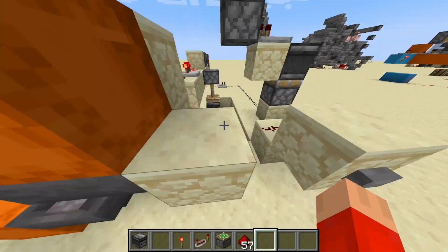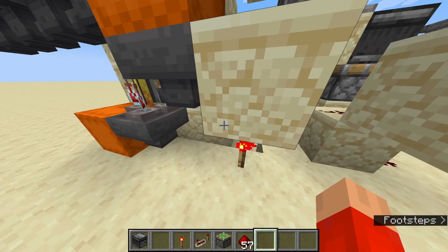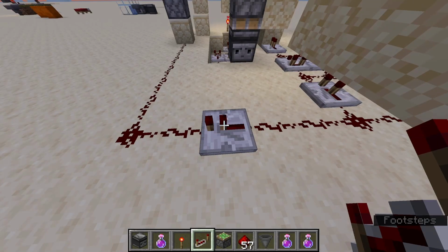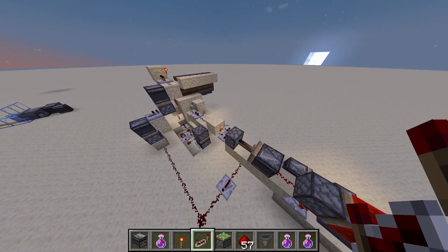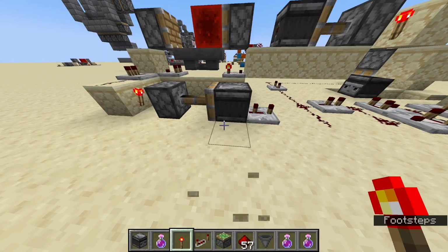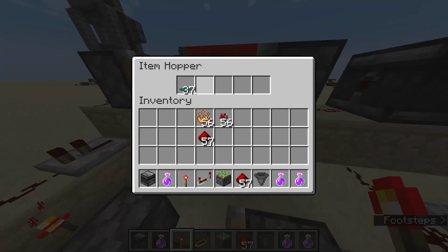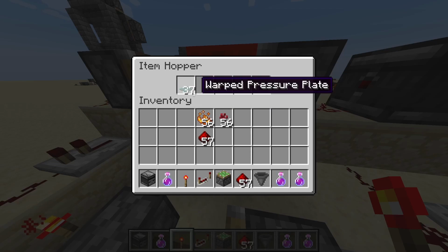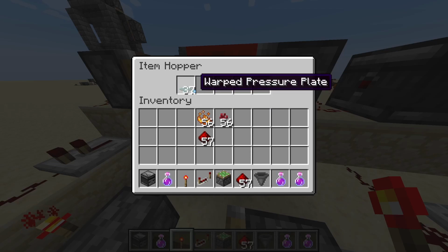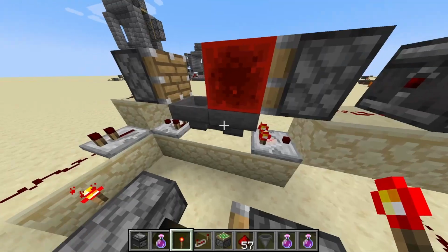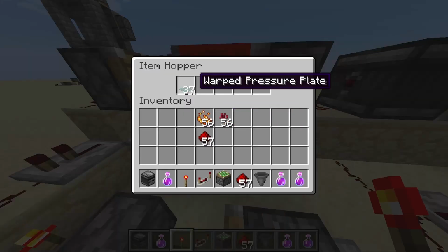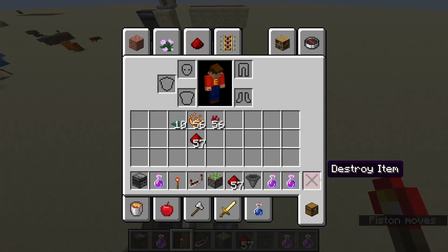Let's see, how do I reset this? Oh dear! This might actually be an easy fix. Just set this to a longer tick register while everything resets, and that might do it. Another thing is this pulse extender took too long, so I'll set it to 37? No wonder I thought it was taking 10 more. How did I put 37? I wanted 27. Okay, that should be better.